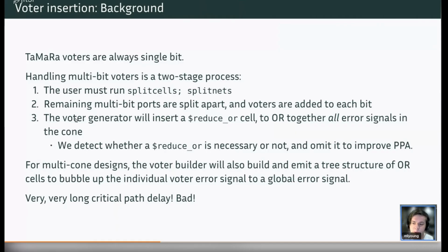And the reason why that's important is because in a lot of cases, if you have an FPGA and you detect that you've been struck by a cosmic ray or some other bit flip has been induced, you want to reboot and reflash your circuit from a known good media. So in space, that will usually look like reflashing your circuit from radiation hardened flash memory or something like that. And those are usually radiation hardened by process, not by design. So those typically cost a lot more. But yeah, you can't really reflash an ASIC. You could reboot it though, and that's why the error signal is important.